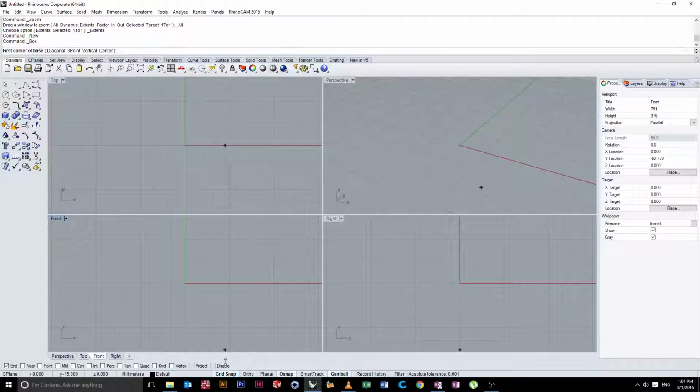If we have grid snap enabled, that'll mean that our cursor jumps between all these little grid points. This can be good sometimes, or it can be annoying, so just remember you can always turn that on and off just by clicking. You see now that our cursor moves smoothly. And we're going to use it in this case to click right on the origin point, or 0, 0.